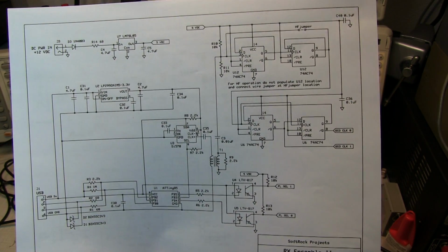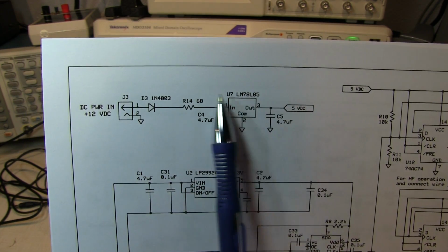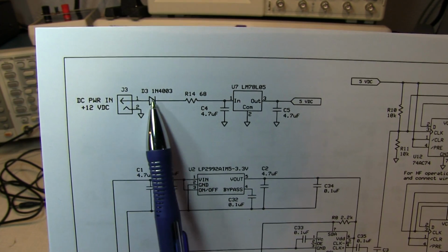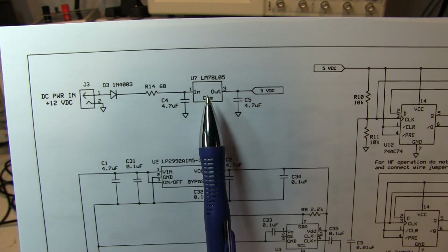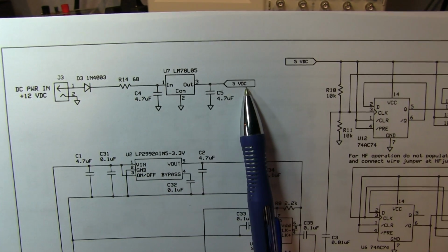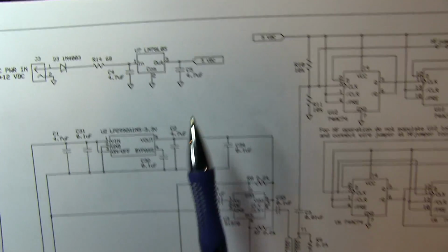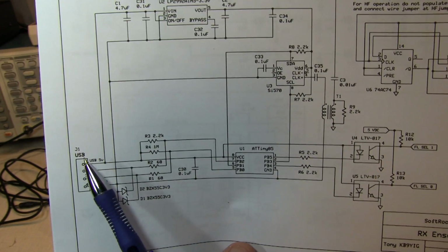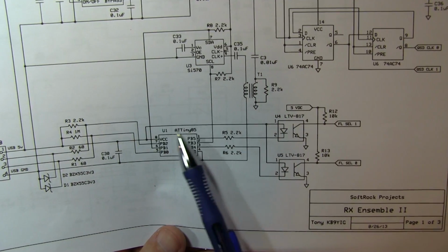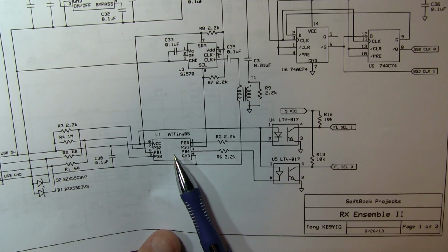Okay, we'll have a look at page 1 of the schematic. Up in the upper corner here is the analog supply voltage for the analog receiver portion of the circuit. Our 12 volts comes in, through a reverse protection diode into a simple linear 5 volt regulator to create our 5 volts DC to power most of the analog circuitry. Now separate from that is this circuit down here. Here's our USB interface to the computer, going off to the Atmel ATtiny85 microcontroller, and it's again doing two things.